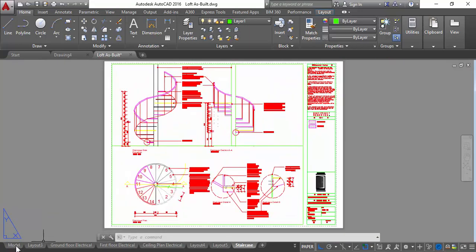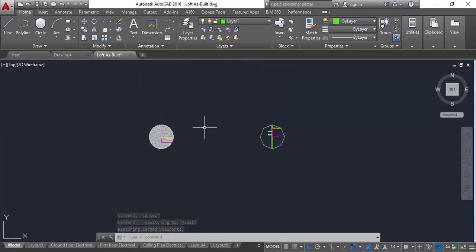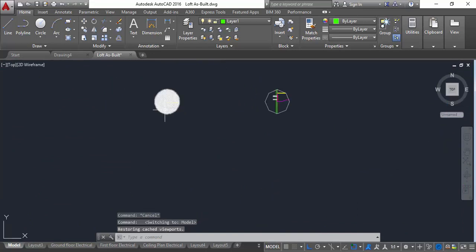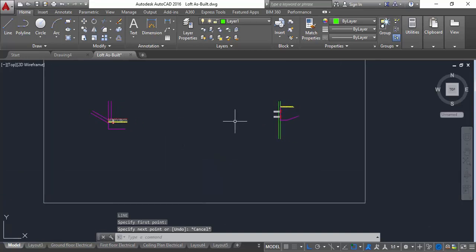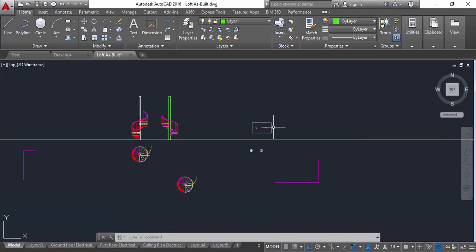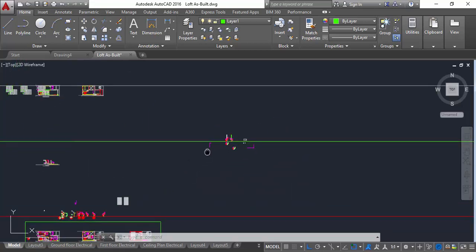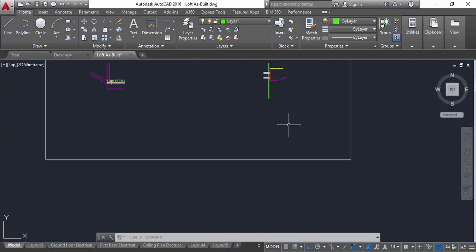First things first, you want to make sure that you have your model of whatever it is that you're drawing, and that you have your details. I see there the hatch has gone a bit haywire. You want to have your details that are actually basically drawn 1:1. So for example, the screw head is 2 centimeters across. That is why in my drawing it is 20 mils. So basically like a normal CAD drawing, but it's incredibly tiny. That is why I've put a box around it so that I can see where they are if I ever lose them. For example, my drawing is this messy, so I can see where they are very easily.